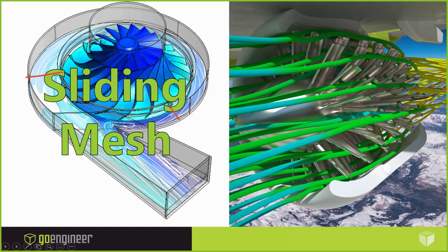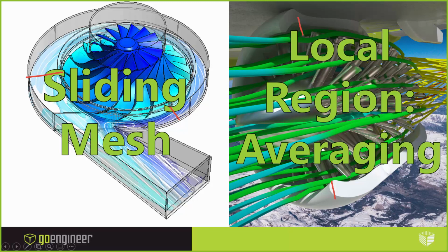In the turbofan, we don't see that variable spacing, so we don't need to use a sliding mesh technique, which saves us calculation time. Instead, what we use is the averaging technique. The blades themselves are not moving. We are saying that the fluid around the blades has reached a steady state.